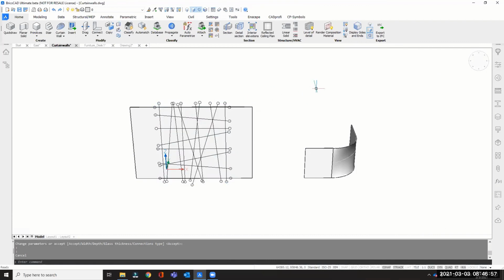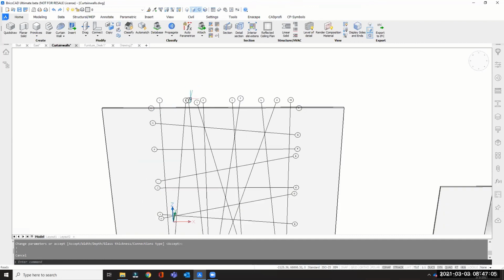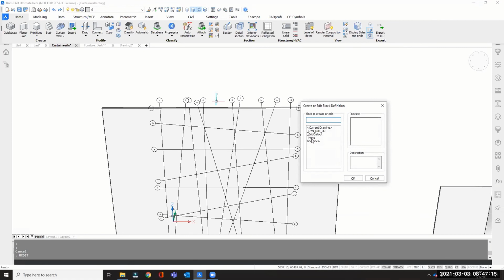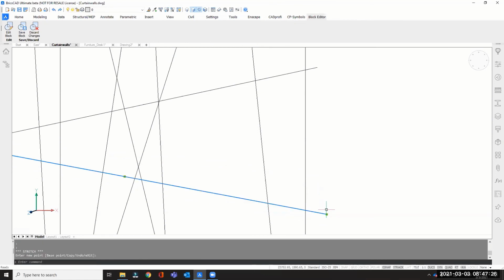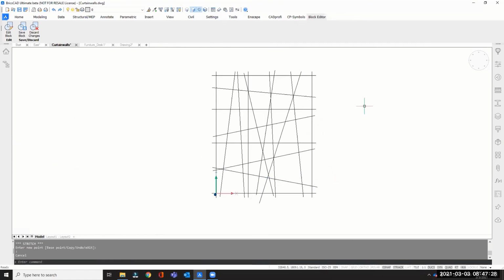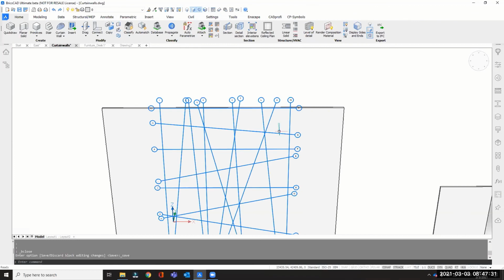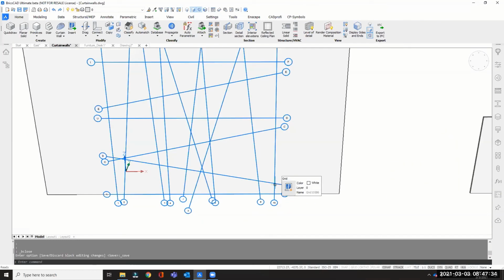So one of the other ways for us to be able to create glazing, this is more advanced glazing. This is similar to the type of grid that we were creating earlier, but it was edited. So how do you edit it? You can actually go to B-edit and select the grid. This is the grid that we are looking at, and you'll be brought into the grid. You can actually shift this around. Let's say we just shift it here, and then that's maybe the change we want, save the block. And you'll go back to this grid and you remember that we shifted this certain line.